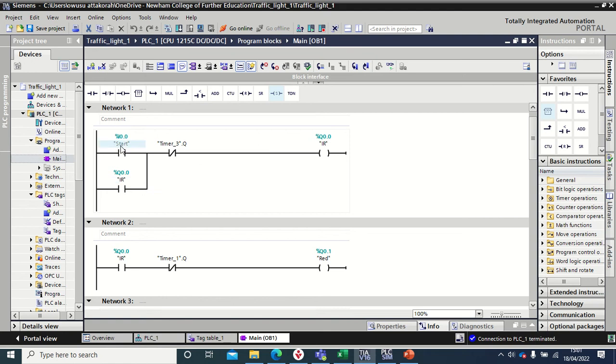Because I'm going to use this start button here, which in my case I would use a detent switch. Okay, I would use a detent switch here. Then actually I wouldn't really need to latch this, but I've latched it. And then I will talk about this normally closed switch here later on.